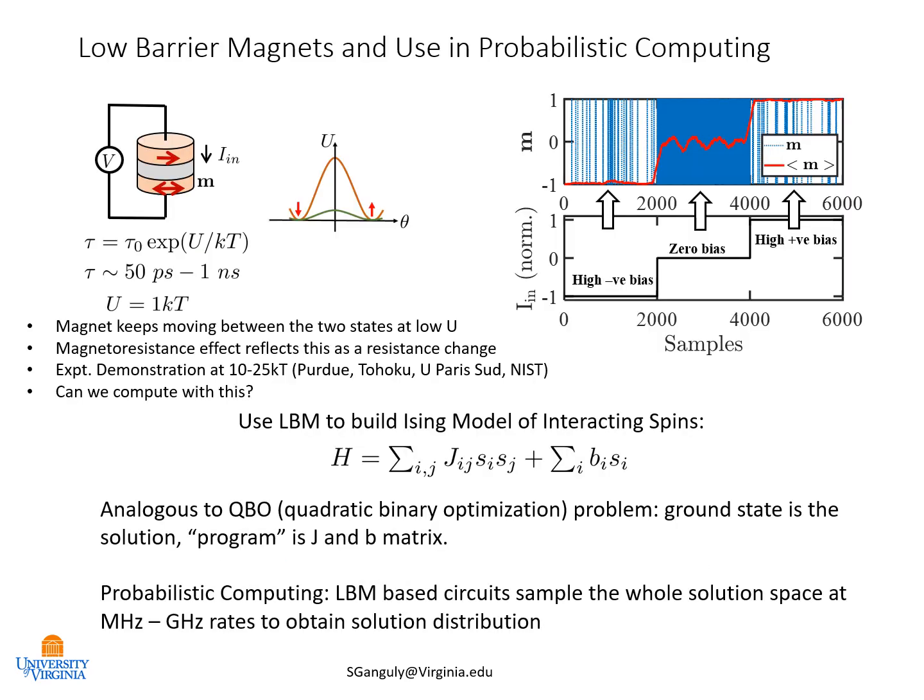State retention in a regular magnet is given by this energy barrier U, which I've drawn in a cartoon. Depending upon how high the energy barrier is, you can get various lifetimes of how quickly a magnet demagnetizes from its own position. In the memory technology industry, the target is a 40 to 60 kT magnet because that gives you 10 years of retention. But for this purpose, we are looking at low energy, like 1 or 2 kT magnets, where your switching time is 50 picoseconds to maybe 1 nanosecond.